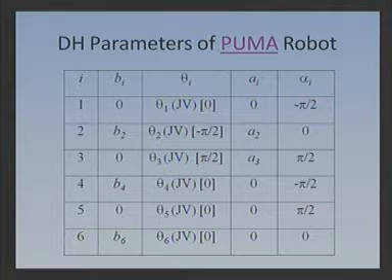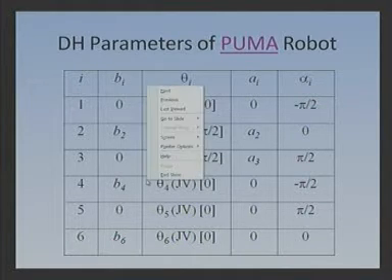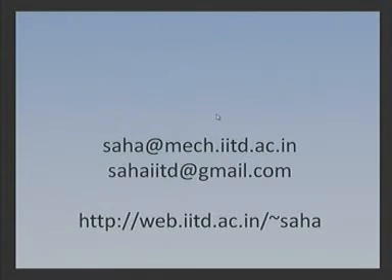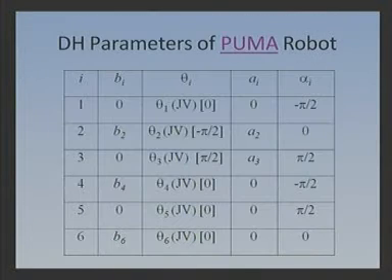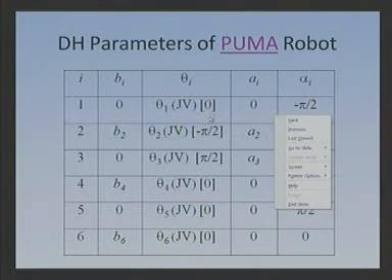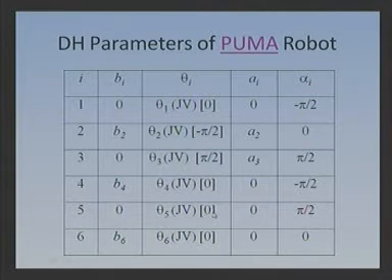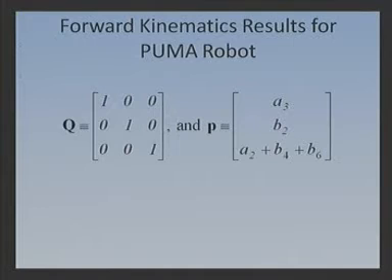What I wanted to verify is, if theta 1, theta 2, theta 3 have these numerical values which I have displayed here, then what will my calculation become? Based on these particular values, if you calculate the orientation matrix Q and the position vector of the origin of the 7th frame, because this has 6 degrees of freedom, the 7th frame will have these values.